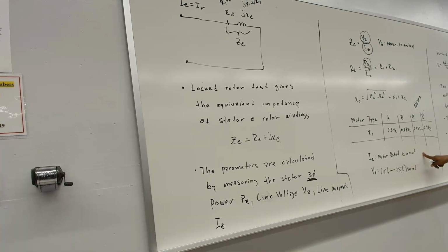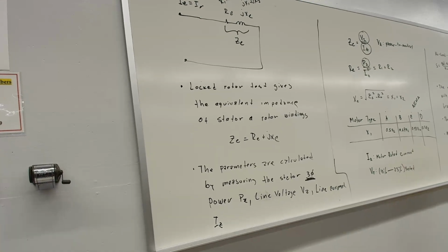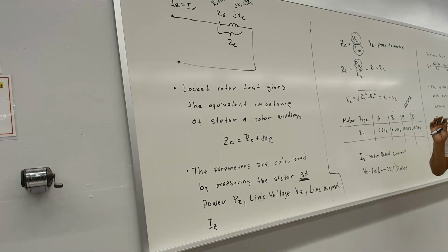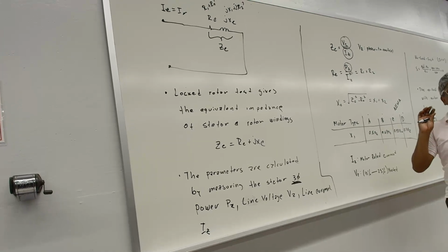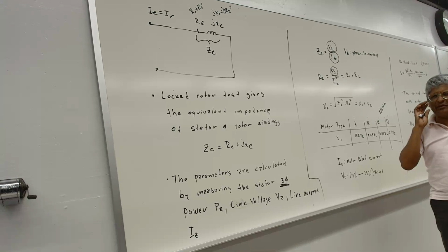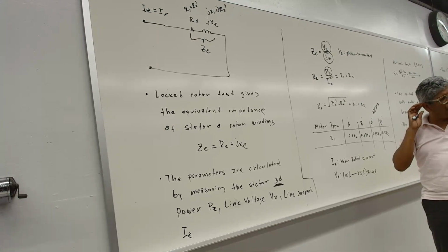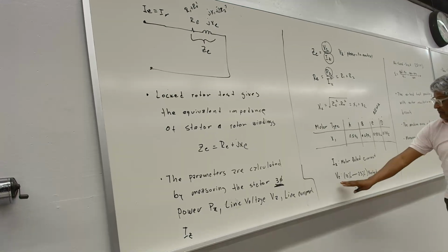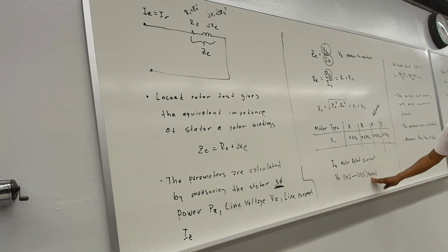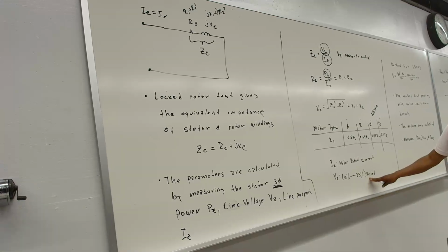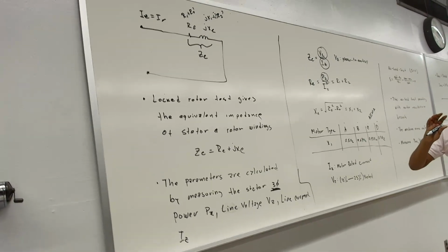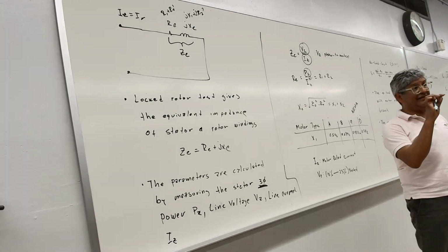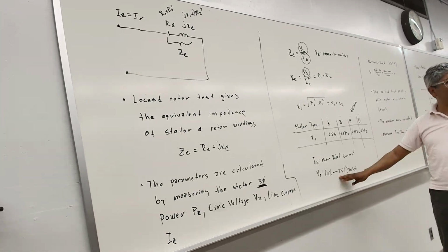And in this case, the current that we're going to push through the motor is the rated current. Remember we're trying to push the voltage until we get some amperage, and I vaguely remember it might have been 2.3 something, but we'll go back to that. You didn't have to get the voltage all the way to 208, but somewhere between. Remember we said keep on pushing the voltage, but do not exceed this current.